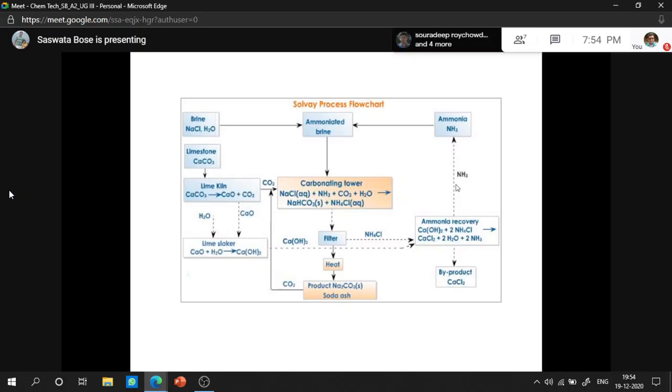Now the problem regarding the crystals of the bicarbonate can be eliminated to a certain extent if you change the construction of the tower. To avoid the situation, the towers are generally constructed with a number of cooling boxes and sloped baffles, so that the sodium bicarbonate settles at the bottom and is pumped as slurry to the rotary filter. From the rotary filter you have the filtrate and the solid residue.